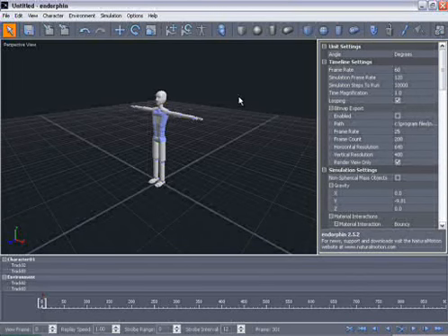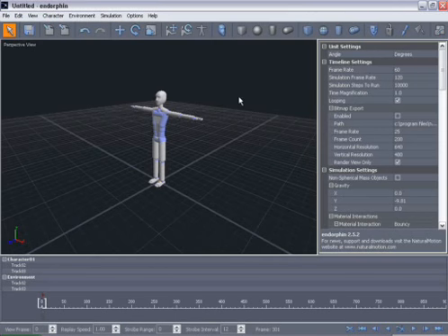In this tutorial we're going to look at dynamic motion transfer, and most specifically the motion transfer event. This allows us to use dynamic retargeting algorithms within Endorphin, but use them within a scene. Normally you do not need to do this for import and export, as that's taken care of with the auto motion transfer, and that's covered in a separate tutorial. The advantage of doing it this way is that you can modify that imported animation by setting strengths on individual joints and then mixing those with the other tools available within Endorphin.